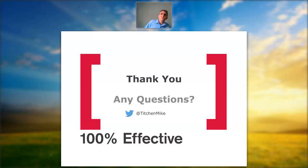There are all sorts of tools you can use for that. You can use the analysis of the 7 wastes, and you can use also tools like spaghetti diagrams, etc., to help you identify that. So the simple answer to that is, create a design that allows the value objects to continually flow. So the flow from input through to a saleable transformed output happens as fast as possible, with the minimum lead time and the maximum process cycle efficiency.